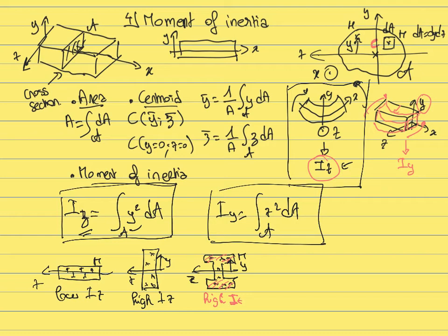For the amount of material that is used, they have a very high moment of inertia, because most of the material is distributed far away from the center of the beam. And because this beam has a high moment of inertia, it will tend to have a low stress, and because it has a low stress, that is going to minimize the risk of fracture. So it's usually a good idea to have a beam that has the shape of an I, because it tends to reduce the stress that the beam is subjected to, because it maximizes the moment of inertia.